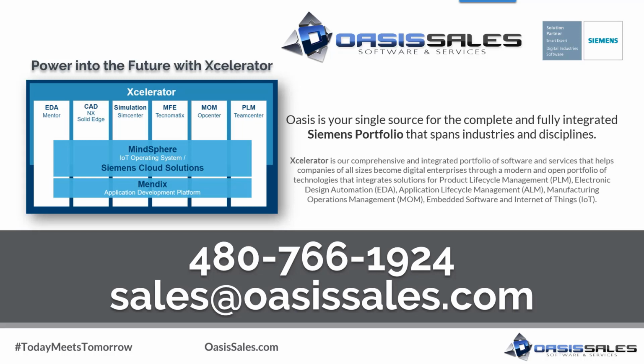There is also a competing standard called IPC 2581B. That's very similar to ODB++, but it's an open file format. So it's kind of like a SAT file maybe. And then there's a couple of others, but really I think ODB++ is the main one that people should be aiming to import into Flotherm, simply because it's the most common.